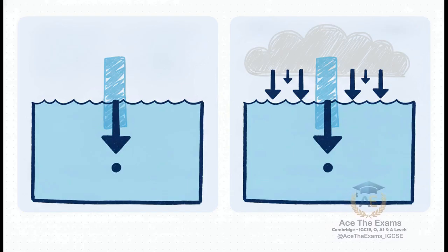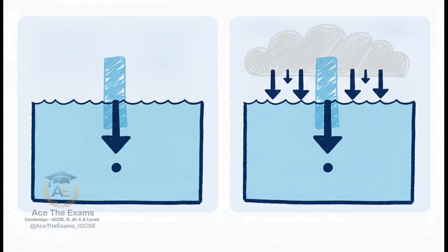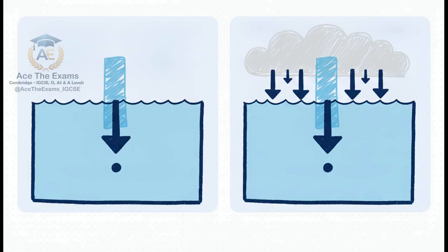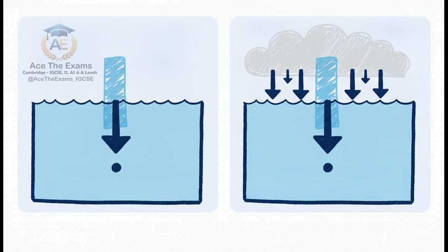Worked example 4F in the textbook perfectly highlights this trap. It asks for the excess pressure over atmospheric, which is just rho g h. But man, if it had asked for total pressure, you'd have to add that 1.01 times 10 to the power of 5 pascals of atmospheric pressure. Missing that single simple addition? Yeah, that literally costs students entire grade boundaries. Don't let it be you.